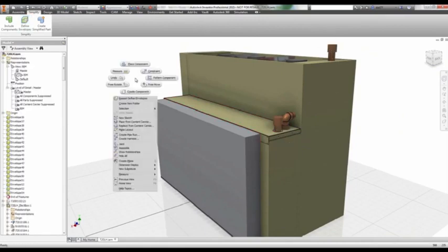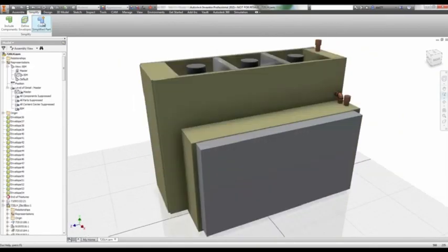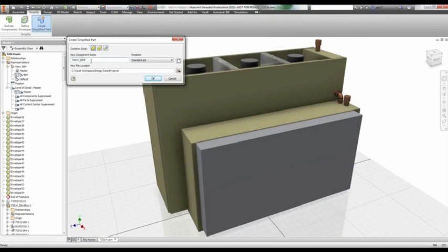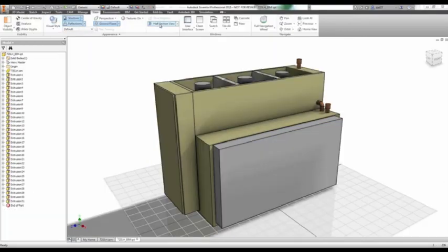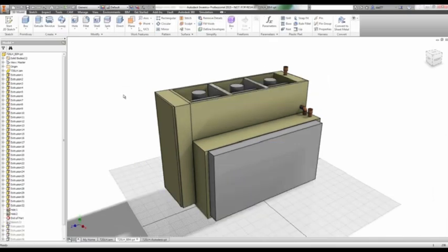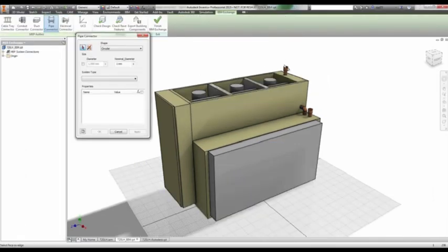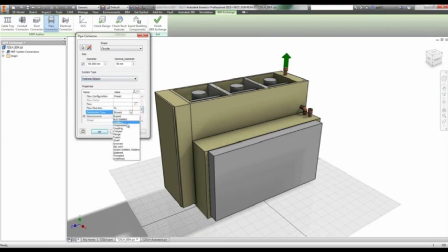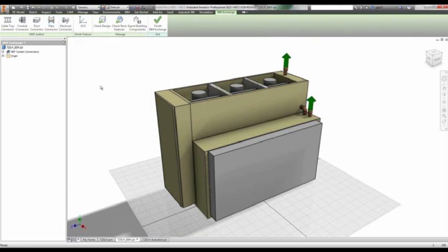So what was originally sheet metal components are now being generated as just solid blocks of material. So straight away I'm removing the IP, or the intellectual property, that I have. But more than that, I'm also removing the overhead and the geometry complexity that means that the model's more heavyweight. You can see there that it's basically solid inside.